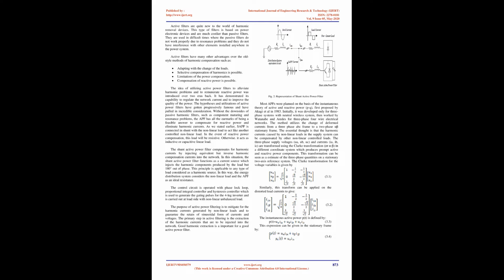Among these solutions, we find two categories that are most used. Active filters, series, shunt, or a combination of both, such as the unified power quality conditioner, UPQC. Hybrid filters composed simultaneously of active and passive filters. 3. Active power filter. Active power filters, APF, have the function of generating harmonic currents or voltages so that the network current or the voltage waves retain the original sinusoidal form.